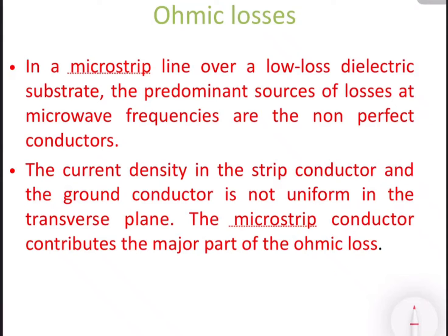And as we all know, a microstrip line has a low loss dielectric substrate, where the predominant sources of loss at microwave frequency are non-perfect conductors.